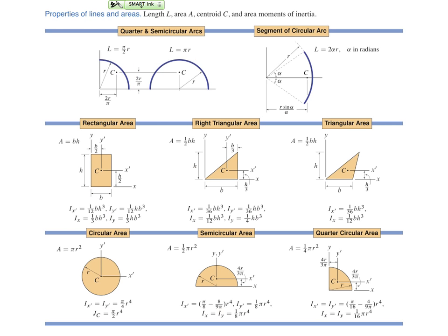Because we often use the parallel axis theorem in conjunction with composite shapes, the centroidal values of Ix and Iy are tabulated for many common shapes on the inside back cover of your book. A couple of points bear repeating. The parallel axis theorem can only be used with the centroidal values of area moments as the reference moment on the right-hand side. This is also emphasized in a column labeled Common Pitfall in the margin in section 10.2.